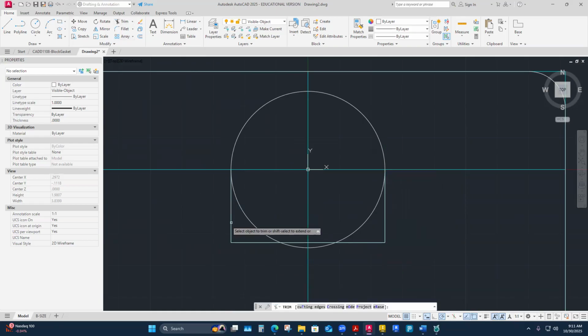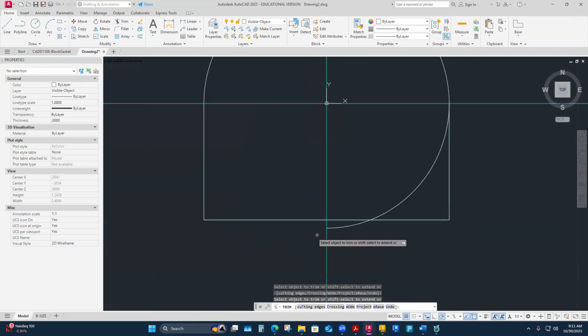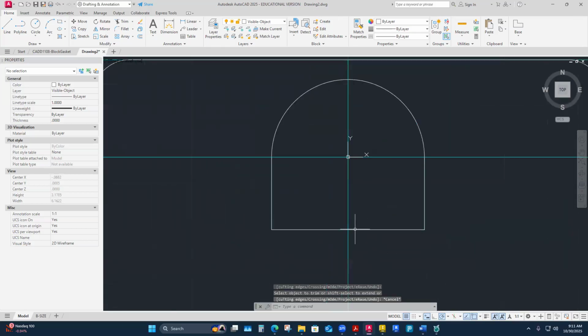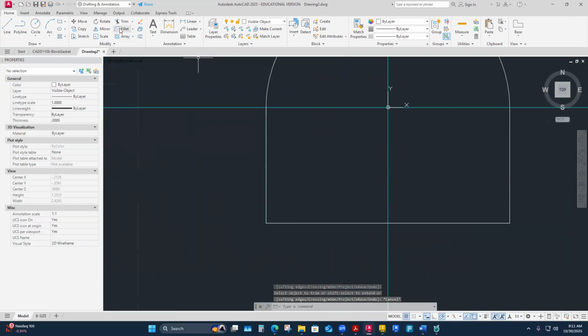Do some trim now. This thing gets trimmed out, right? And the last detail on that is I will put in its fillet of 0.06. So I need to set a new radius, 0.06. It's essentially a real shorthand notation of a 16th radius. 0.0625 is 1/16 of an inch.